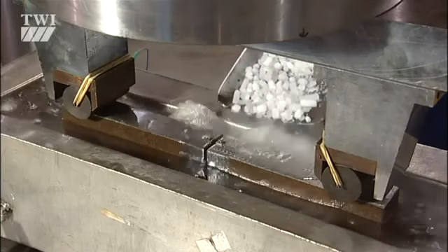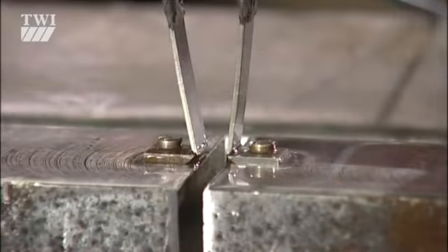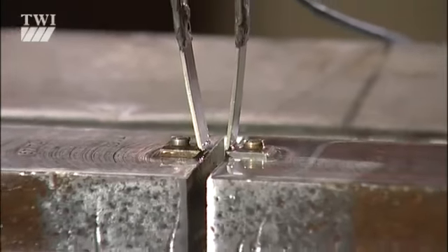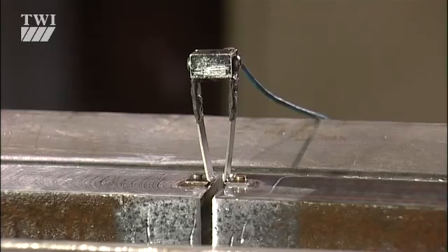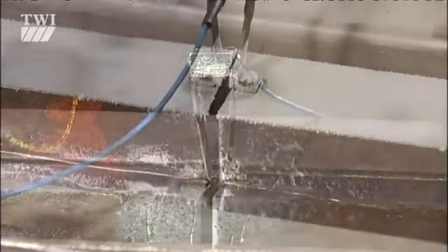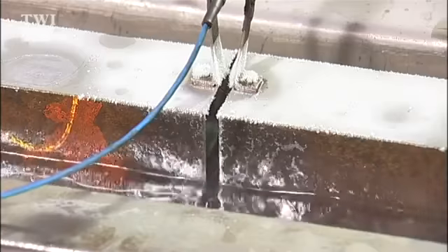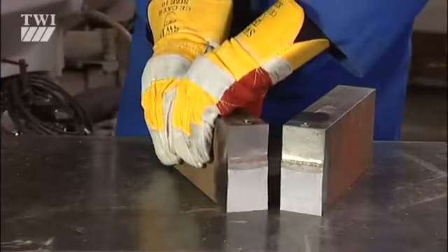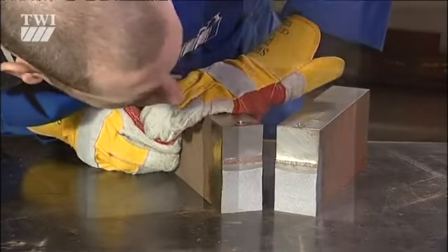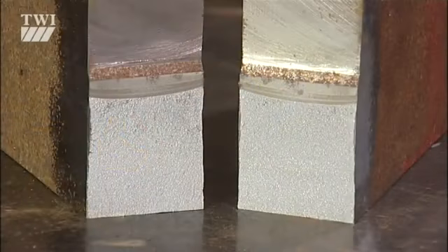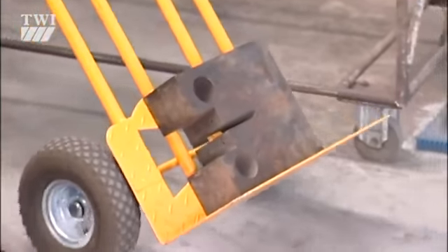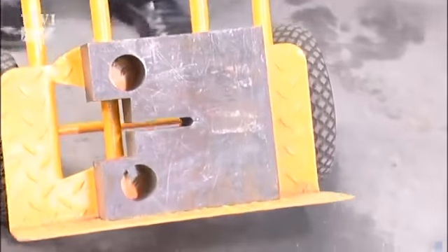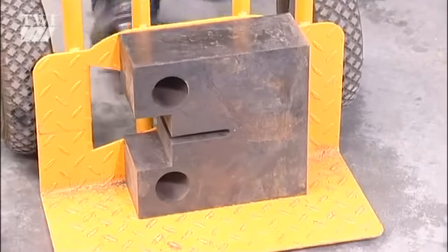As bending proceeds, the crack tip plastically deforms until a critical point is reached, when the crack has opened sufficiently to initiate a fracture event, and either partial or complete failure of the specimen. Many specimen geometries may be used, and this type of test piece is known as the single-edged notched bend, or SENB specimen. The compact tension, or CT specimen, may also be used to characterize fracture behavior.